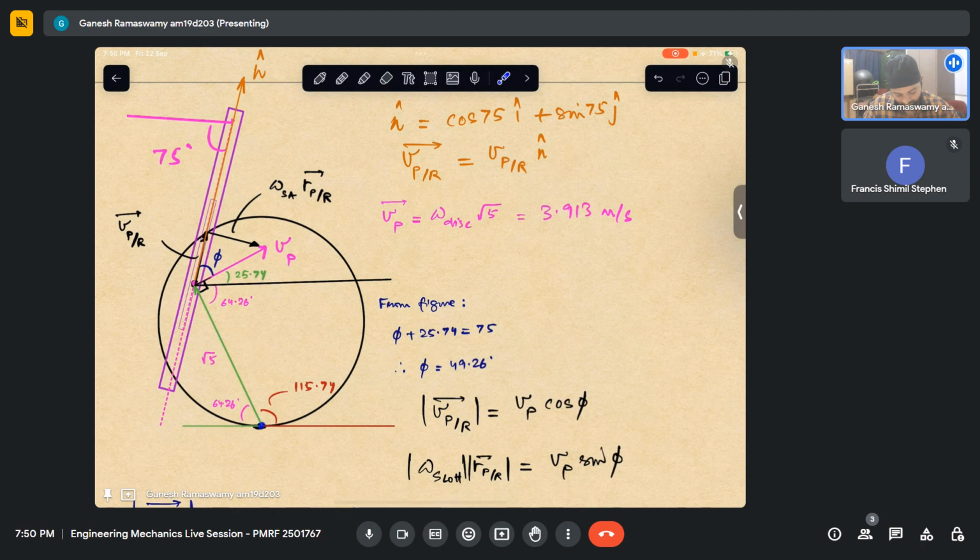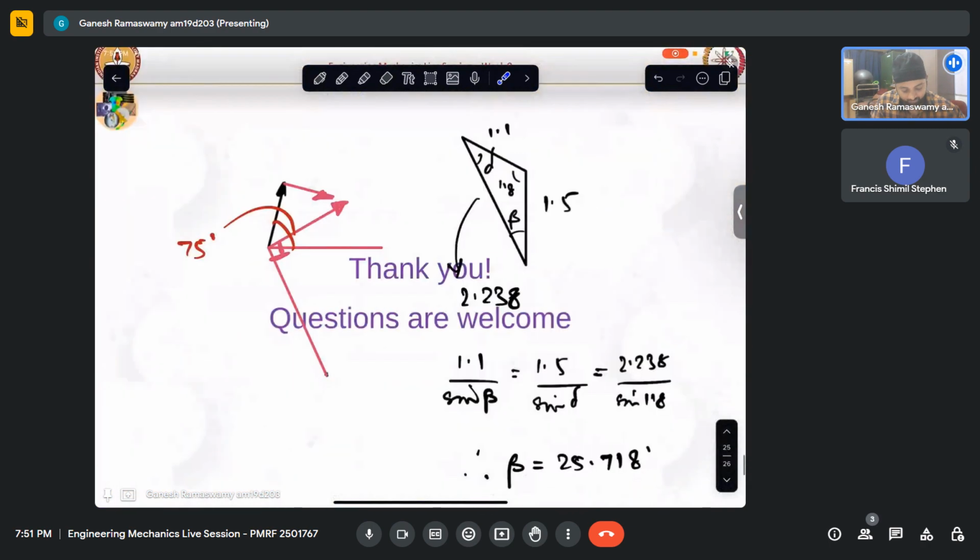Whereas from the absolute motion, from our normal relative motion analysis with non-rotating translating axis, if I attach the non-rotating translating axis here, I know this will have one centripetal acceleration, this will have one tangential acceleration, and then this point itself is having an acceleration towards the center by virtue of that being the ICR. So the sum of these three will give you the acceleration. So that is all that needs to be done. Let me just write the equations for that.